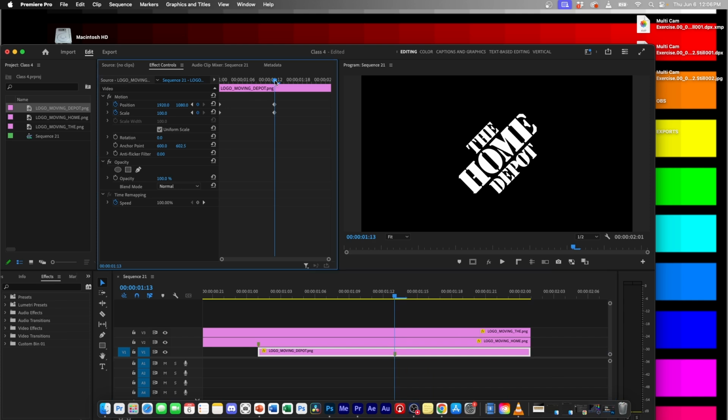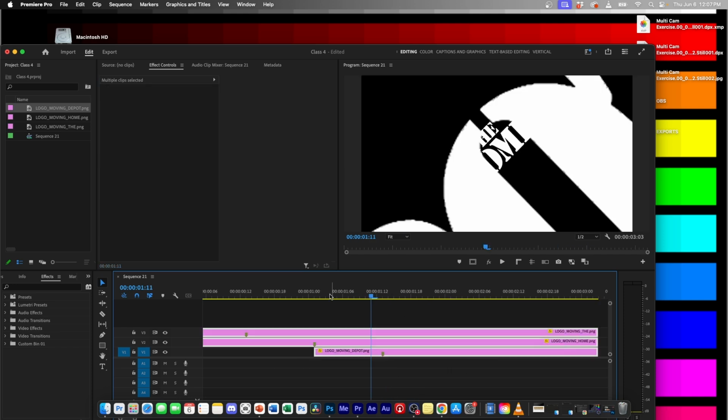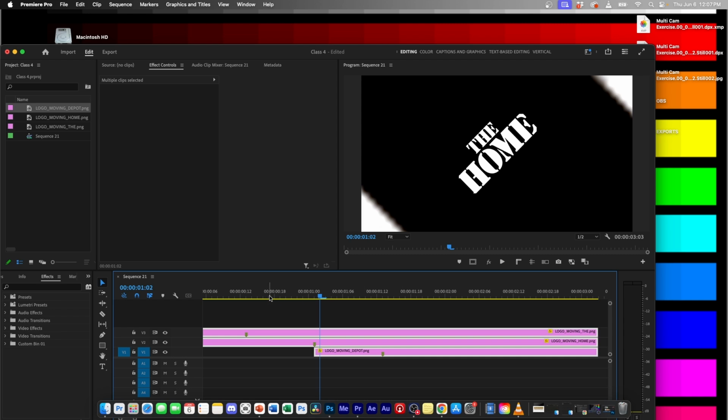Right here, go in here. I'm going to hit 2 frames over. And I am going to, actually, we're going to set the base to, because I want to go a little past it. So I want to go like 95. And then 2 frames over, I want to set that to like 115. And then 2 frames over, we set that to 100. So this is what that looks like. It's going to add like a little bounce to the end to make it look like it hit the ground and then like bounced and got into place.